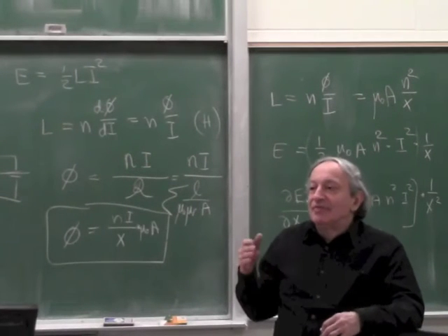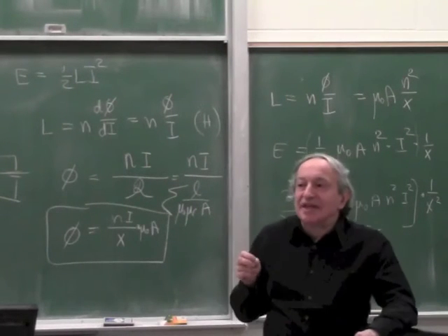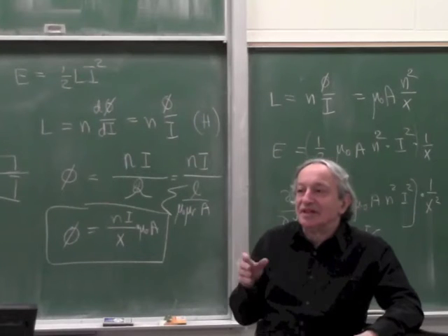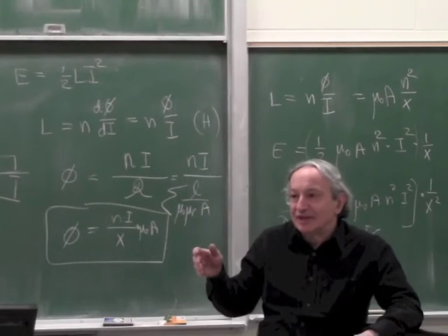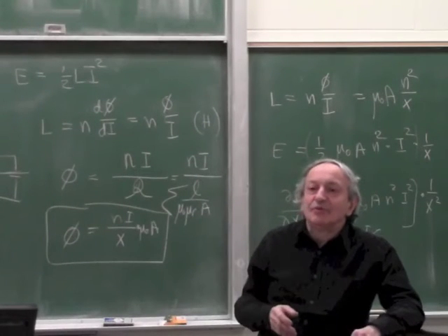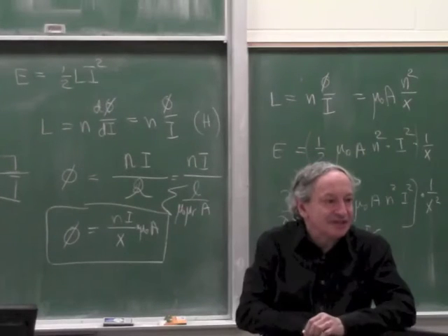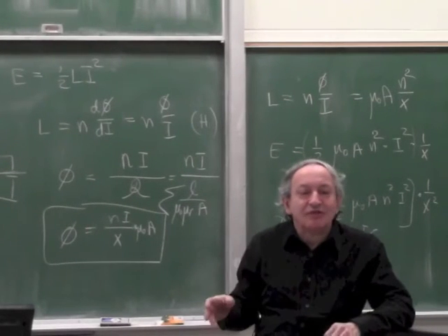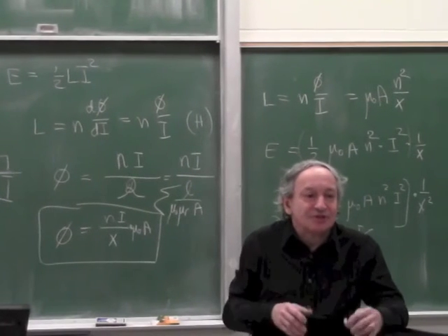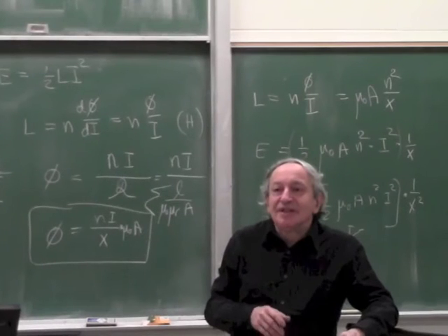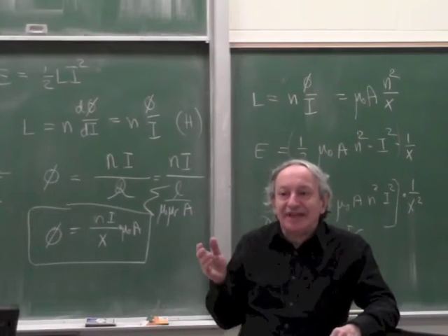Because you have to make sure that at the highest gain, the phase shift is less than 180 degrees if the gain is more than 1, right? So basically the worst case for stability is when it's almost closed, where the gain is highest. You have to make sure there's no phase shift, you have to put some special limitations on the servo, but then at any other position it lacks gain.